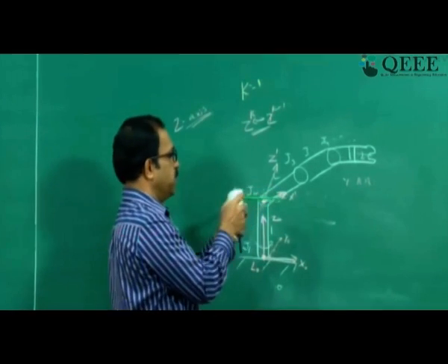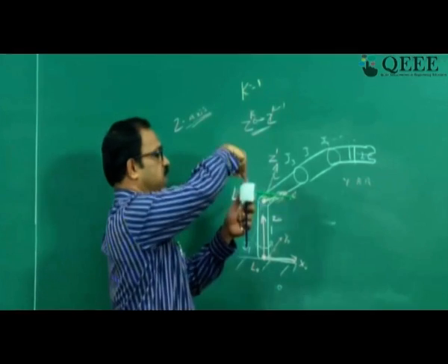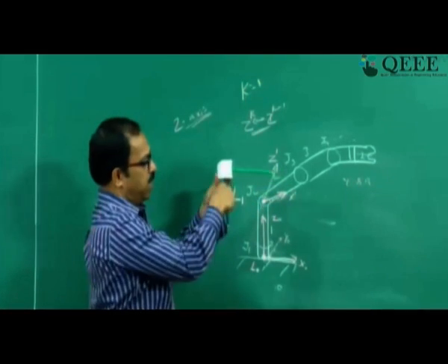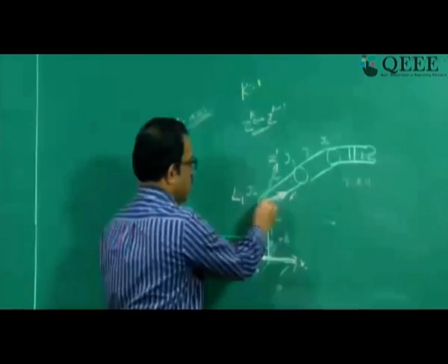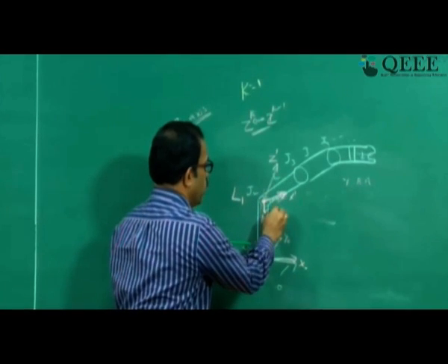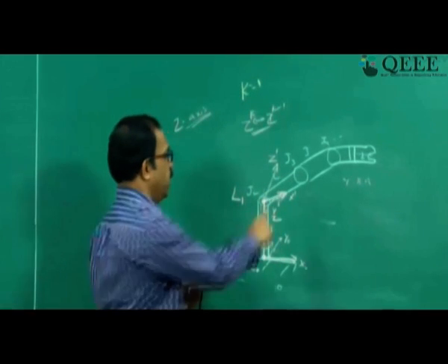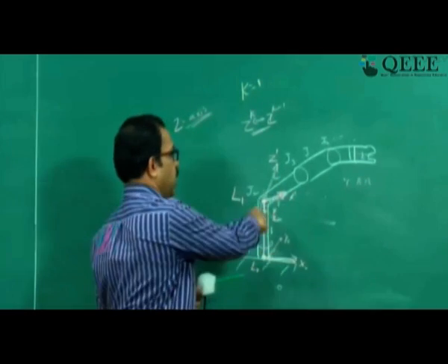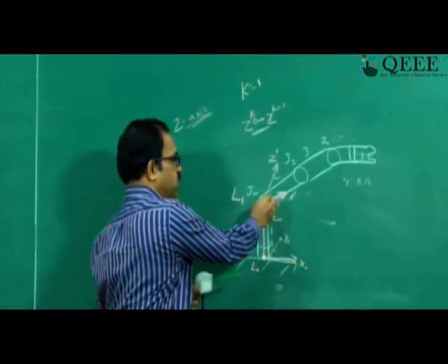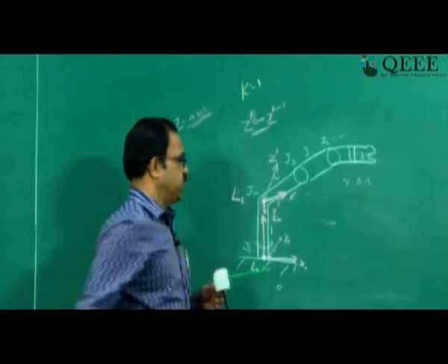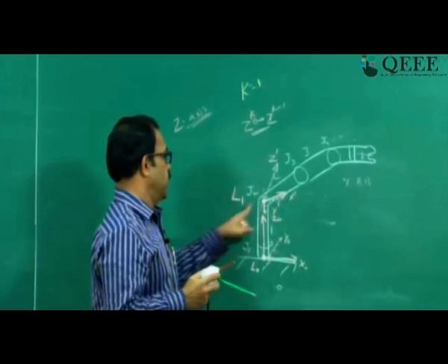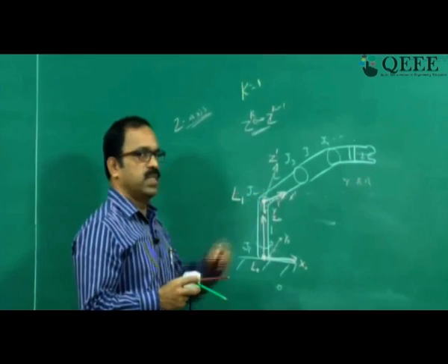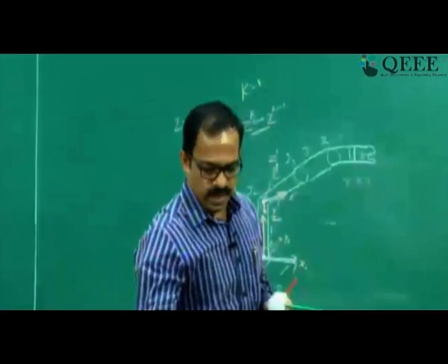So this is the X axis, this is the Z axis, the red one is the Z axis, and this will be the Y axis. So Y will be like this. So Y1 will be like this. So you have X1, Z1 and Y1, the three axes identified. This is the coordinate frame assigned to the second joint. So that is the second step, identifying the coordinate frame.